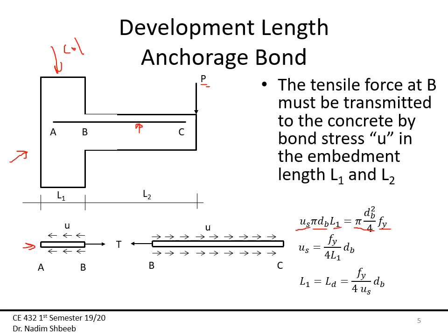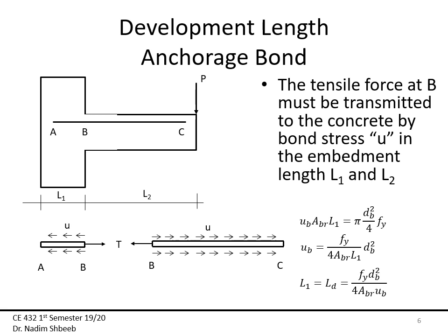It is much more complicated than that, but at least it will give you an idea how that length L1, which in the future I'm going to call LD, relates to the slipping of steel and concrete. We can notice, first of all, the yield strength of steel, the diameter of the bars involved, and then the slipping bond stress, which we actually don't have accurate information on. So this is from the bond stress. Then, because of the presence of the deformations, we also have the bearing stress, as we explained. So now this is my bearing bond strength.